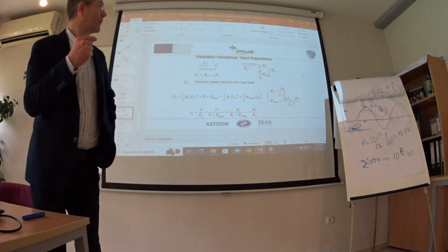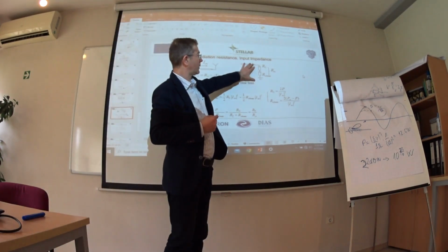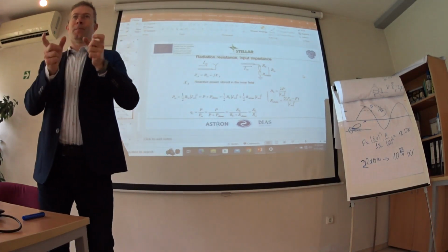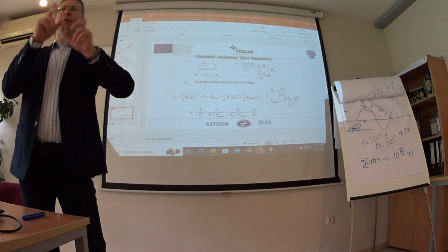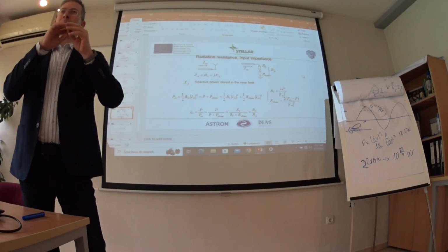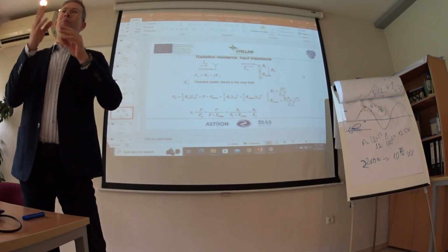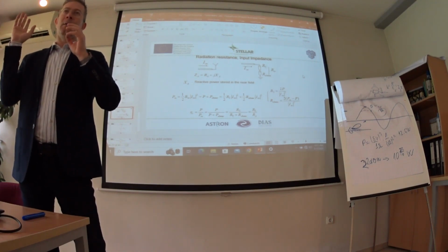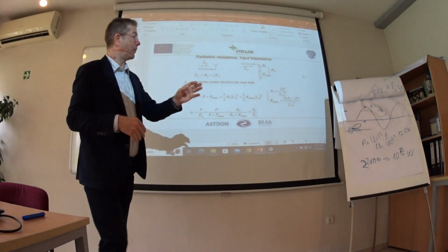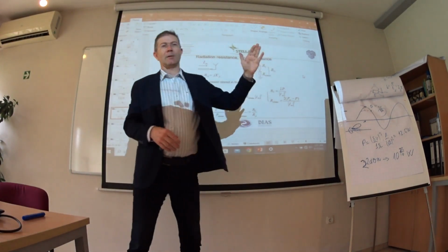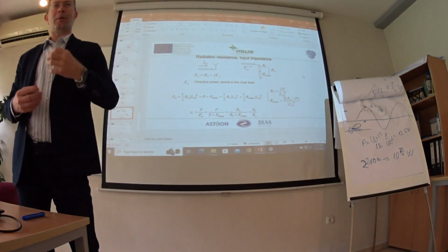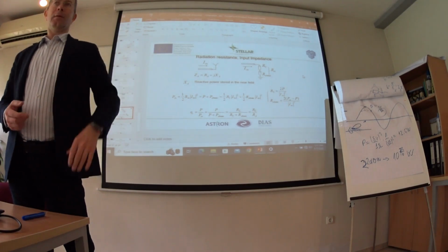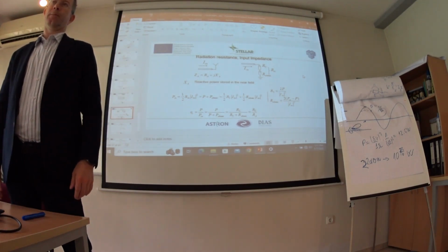From the point of view of the cable, the generator, we see both of them. We don't know what the ratio is. But we don't care. If we design a generator or transmitter, we say the antenna has an input impedance of 50 ohms, period. We don't care what happens with that power. Once we start to make the communication budget, we start to care: 1 watt is coming, but how much will be emitted? And then radiation resistance comes into place.